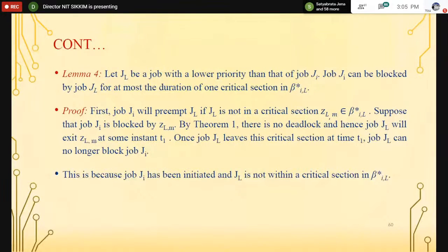And therefore we are interested in the deterministic duration of the blocking of any task. But in non-real-time systems, when you talk about the critical section, you never bother whether your process is going to be 1 hour in the critical section or 2 hours or 3 hours. It depends. But in a real-time system, we are very particular about how long or how much delay the critical section is going to impose in the system, and therefore the solution has to be provided.